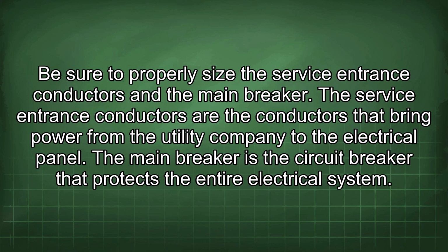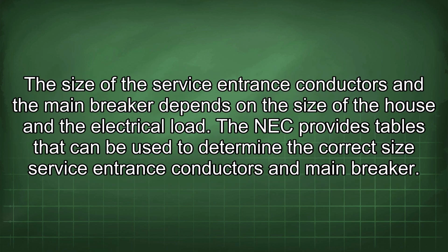Be sure to properly size the service entrance conductors and the main breaker. The service entrance conductors are the conductors that bring power from the utility company to the electrical panel. The main breaker is the circuit breaker that protects the entire electrical system. The size of the service entrance conductors and the main breaker depends on the size of the house and the electrical load. The NEC provides tables that can be used to determine the correct size service entrance conductors and main breaker.